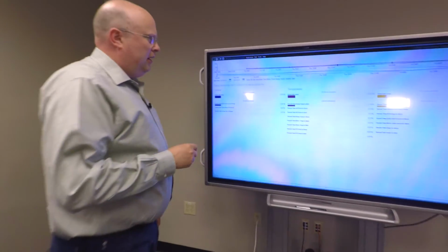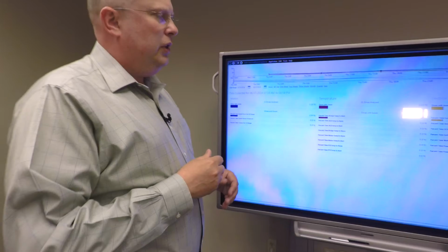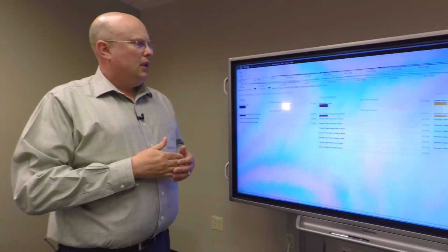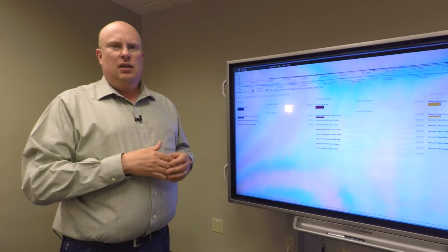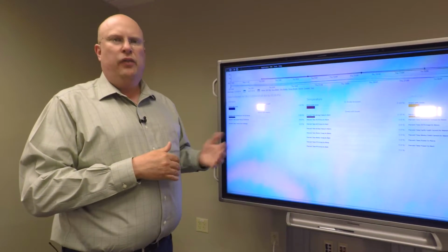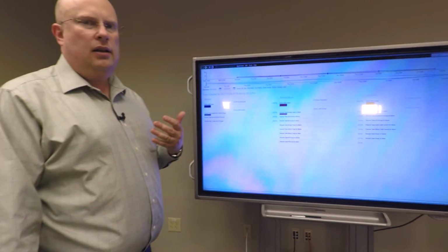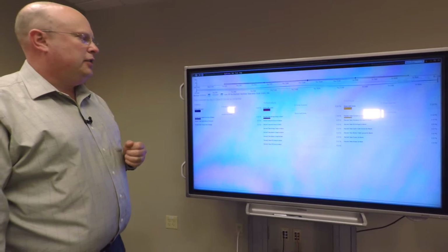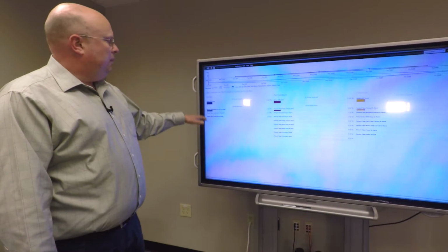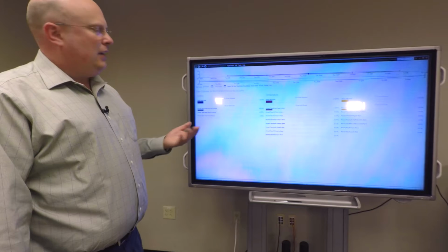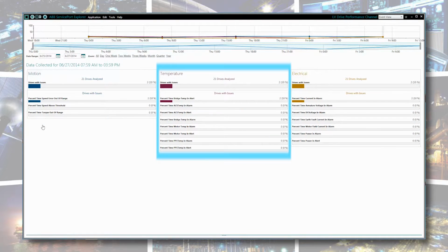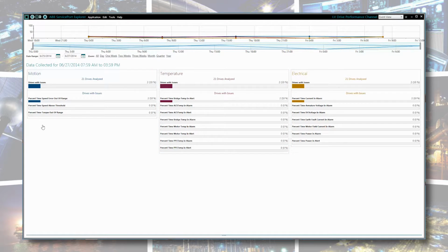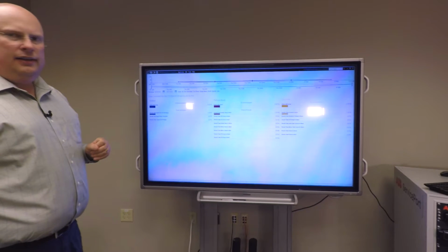We, of course, have a number of other ones for the electrical. We're checking the DC voltage. That's the DC voltage in the drive. If that goes too high or too low, it will affect the performance and could lead to a failure. We look at the speed, if they're out of range, if they're matching or not. Motor temperature, both the measured and the calculated. The power going out to the motor and so on. So we're looking at a lot of things on the signal part.